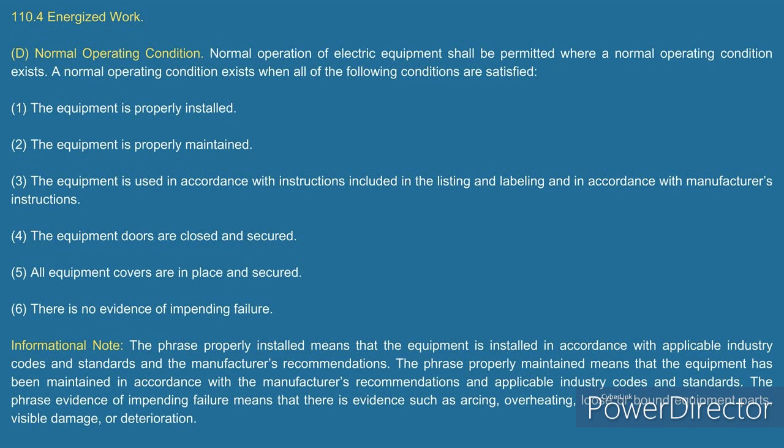A lot of times what we'd have to do when we're walking in there was when they were doing a ramp down and they ramped the whole plant down, you can go in there and do a whole list of tasks. Not opening the equipment, not exposing energized parts, you don't have to establish an electrically safe work condition, but you can go in there and check breakers, make sure all the breakers are clean, make sure all your labels are in place, make sure everything's good to go.